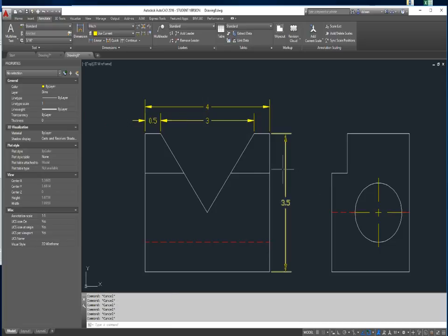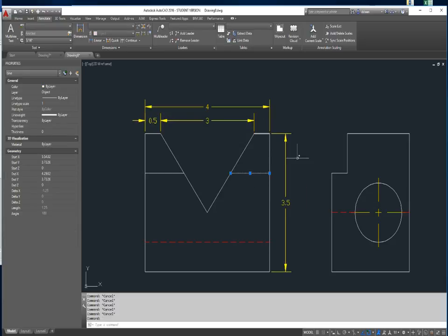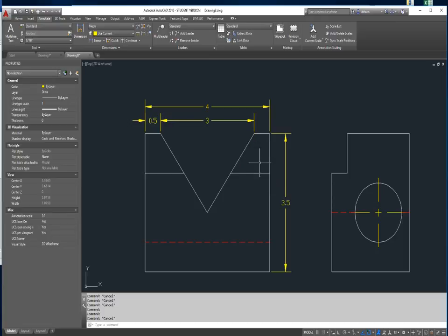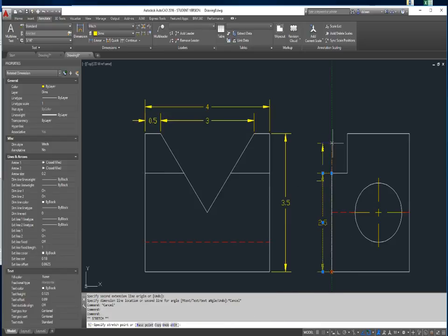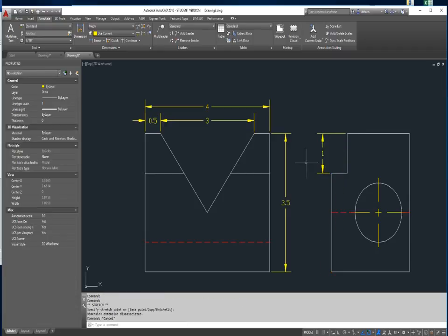And you want a dimension in the correct view. So like this is clearly this line here. This is the same feature, except here in the front view, this is not a great place to dimension it. It doesn't completely describe what's going on. So I would dimension probably my biggest feature there. If that's not what you wanted to dimension, then you might want to dimension from there to there and show that that's 1 inch.